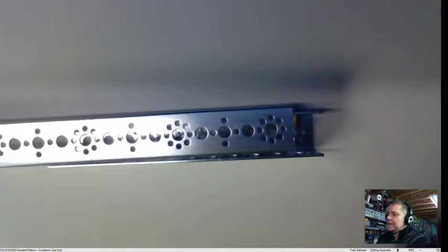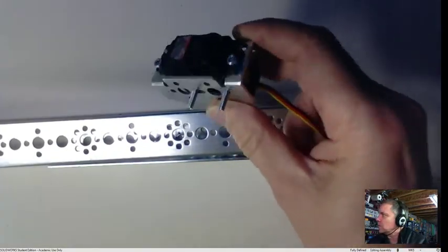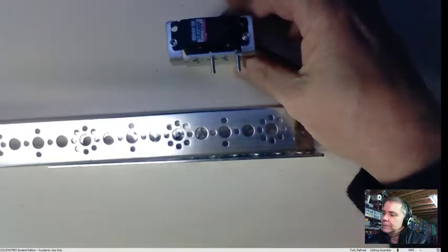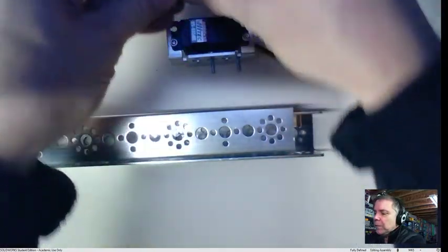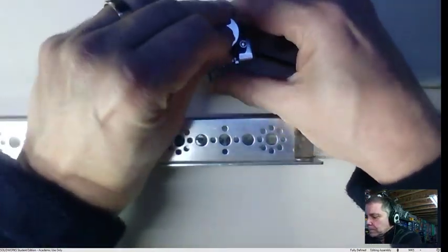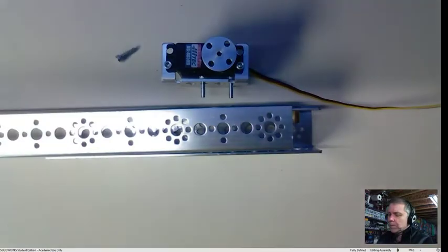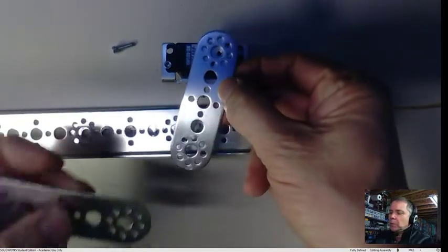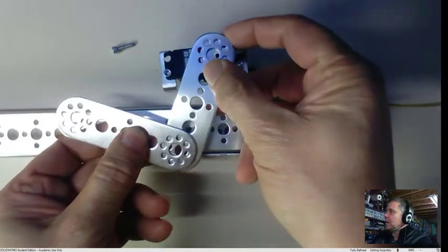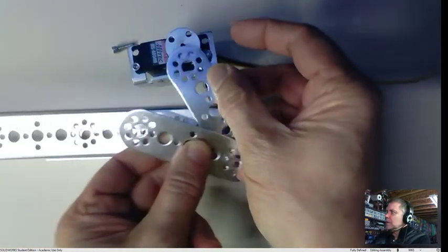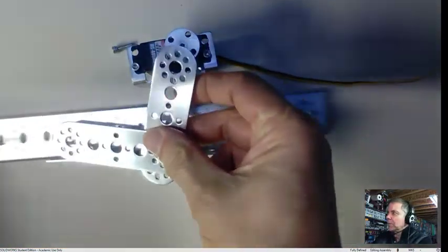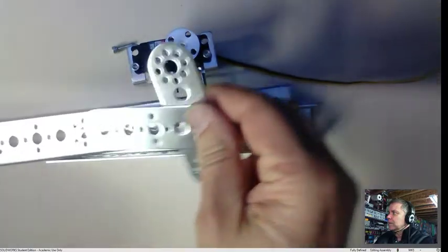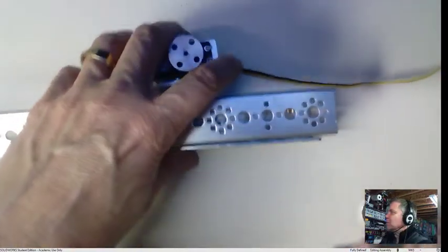We're going to take a servo and mount it in its little servo holder that Tetrix provides. We're going to get a circular horn and we'll just mount that on top of the servo. We'll attach on a couple of swing arms, one like that and one like this, so as the servo turns the swing arm is going to move back and forth. And this end of the swing arm is going to attach onto our bracket. So as the swing arm moves back and forth, hopefully our real device will move back and forth too.